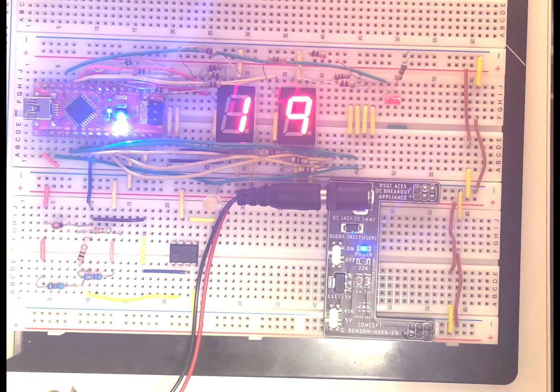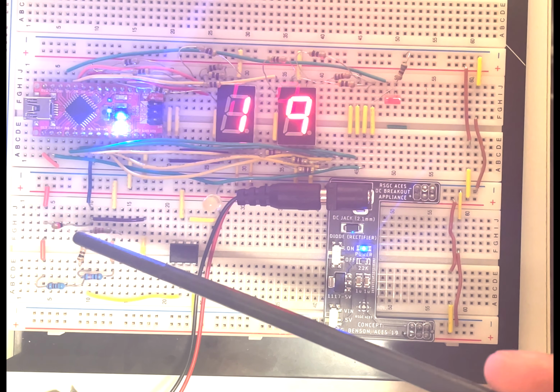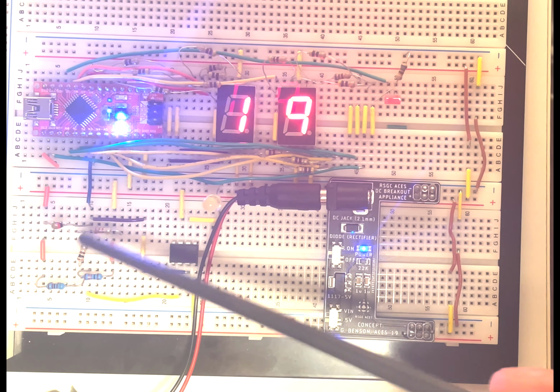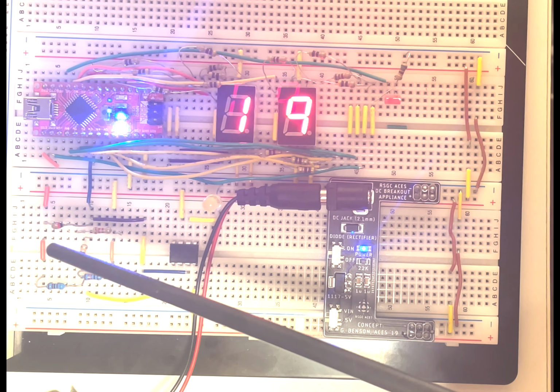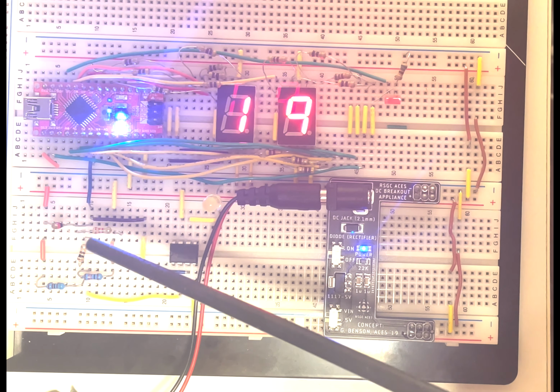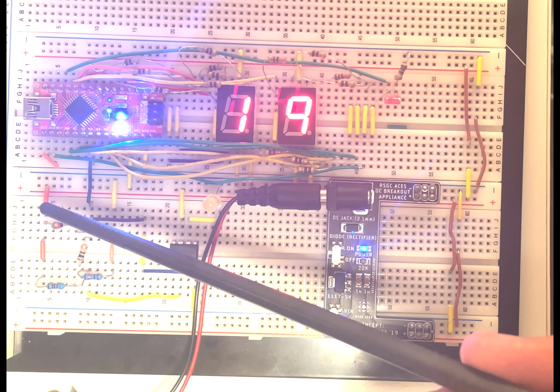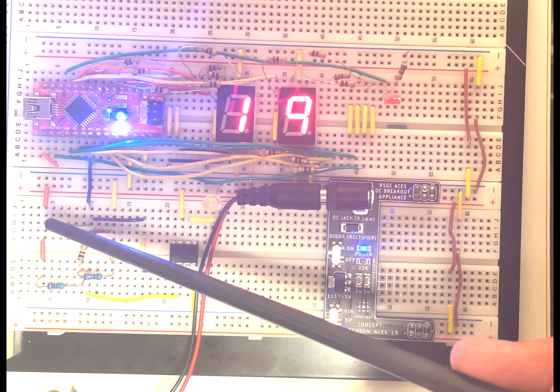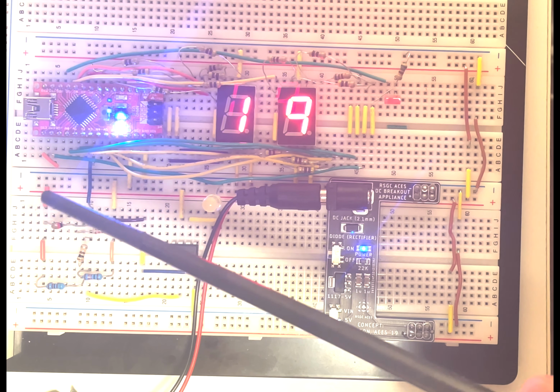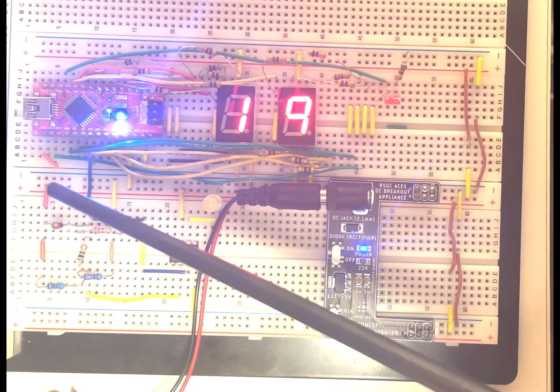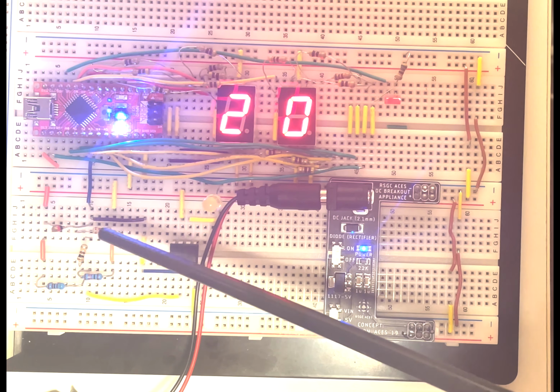The first part of this circuit is the Wheatstone bridge. The Wheatstone bridge contains the actual temperature reader of the circuit, which is called a thermistor. A thermistor is a device that changes its resistance based on the temperature around it. In my case, I am using a negative temperature coefficient thermistor, which increases its resistance as the temperature decreases. So when I hold my hand here, the resistance decreases in the thermistor. And that is being used in this Wheatstone bridge.